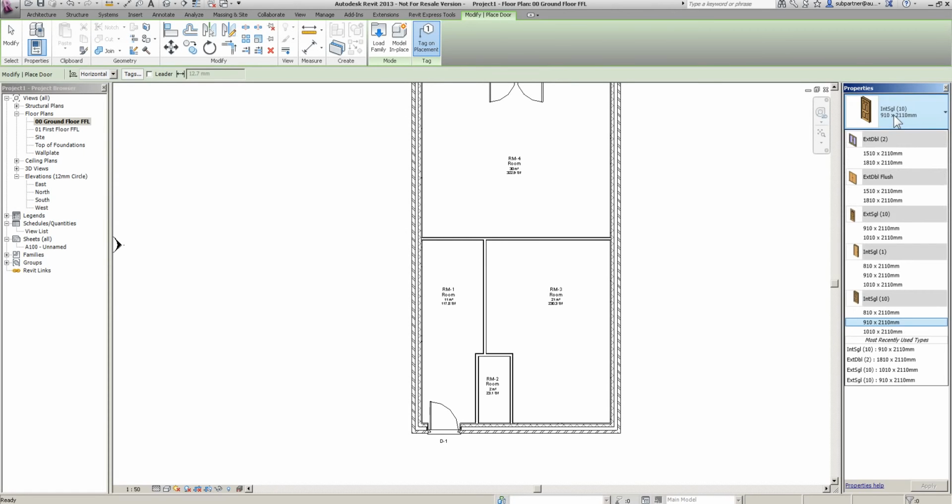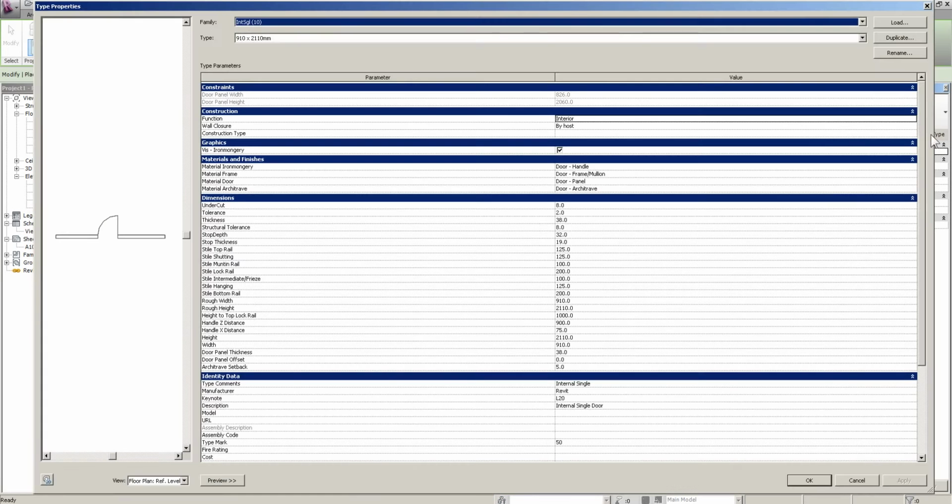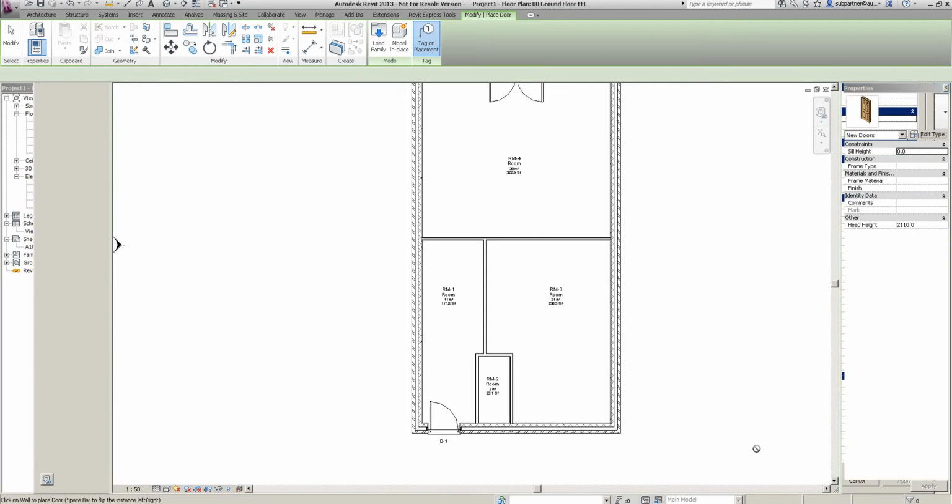Okay, there we go. Now I'm going to put some 910 doors in. These work quite nice with the metric door openings, okay, because if I go edit style, edit type up here, if we look at the 910, this is a structural opening. It gives you a door panel of 826, which obviously, as people in construction know, that's a metric door. I quite like that. It's got the tolerances outside of the frame, in the frame between the panels, and then obviously the frame sizes and all of that collaboration, so it works quite nice.